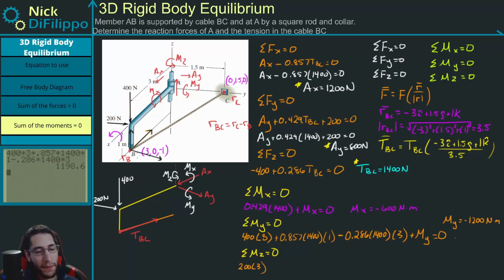All right. And what's happening with this tension force right here? So the up force is parallel to the z. The x force is actually going to go through the z-axis, so that's not going to have a moment. And this y force is going to create a moment about the z.